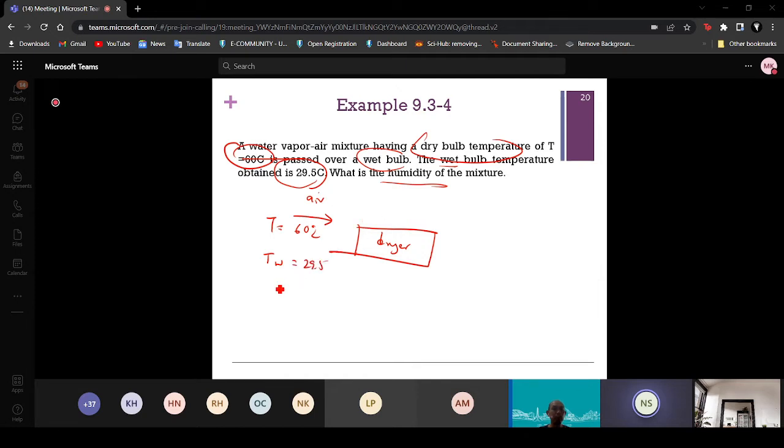So they ask you to find the humidity here. Basically it is finding the properties of one stream, not the other side. To find the other side, you would use the adiabatic curve line. But in this case, when you want to find T wet bulb, because its properties are like adiabatic saturation properties, the method to get T wet bulb is also the adiabatic saturation curve method.